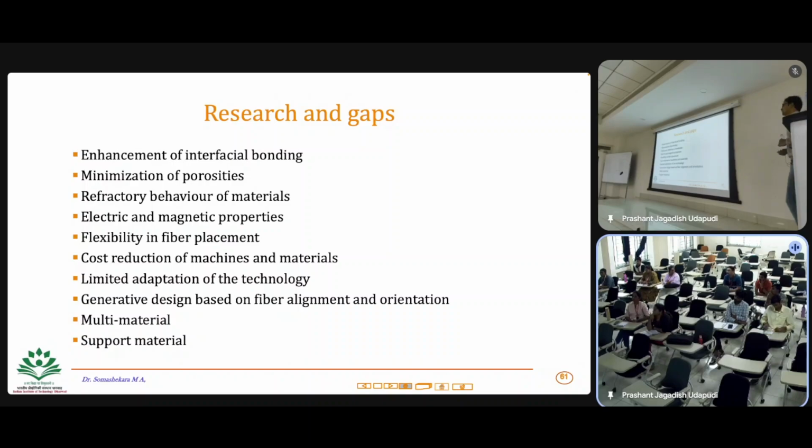One is, you increase the temperature of the material or the nozzle temperature, so that you can improve the bonding between the layers. That is one. The second one is to make sure your environment is controlled. Usually we keep anywhere from 60 to 70 degrees Celsius environment maintained, so that the temperature variation is less.